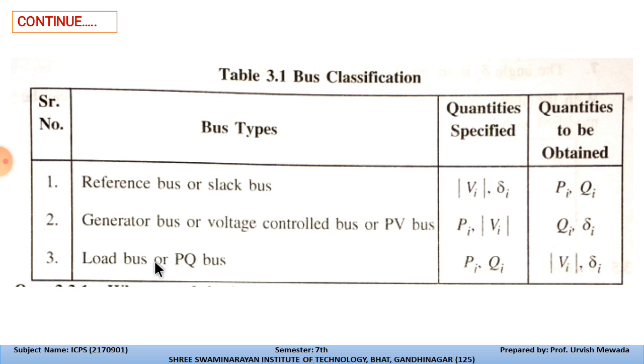And for the load bus or PQ bus, the active power and reactive power are given, and we need to obtain the voltage and the phase angle from this given data. So this is the summary of the bus classification. We can memorize these things with the help of this tabular form.